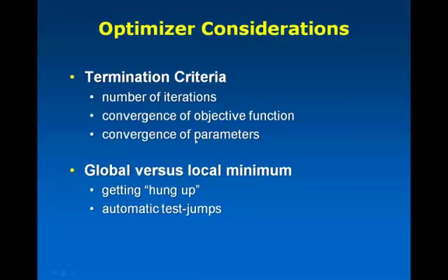So here we can see there's a number of settings that you use for the termination criteria I mentioned before. Basically, it's the point at which it's going to stop its convergence. So you can either do it based on the amount of parameters, or you can have a total number of iterations. It basically takes whichever one of these happens first that brings it to a halt.